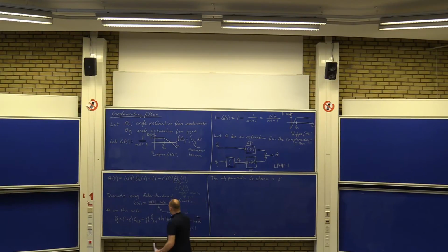Okay, and what does this really mean when we change gamma here? So we saw that H was given, right? So sampling period, we can't change that, but we can change alpha. So if we take a large alpha, that means that this quotient will be close to 1, right? So gamma is close to 1 results in a low cutoff frequency.